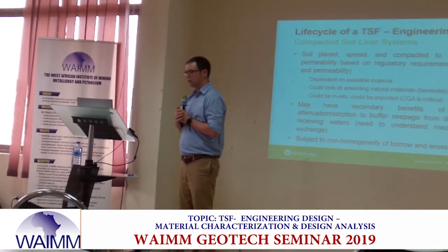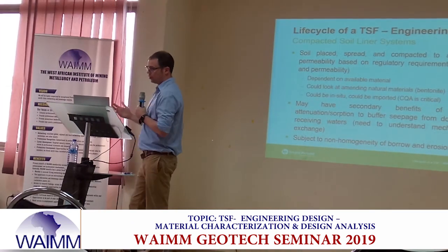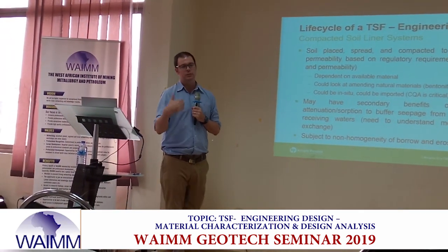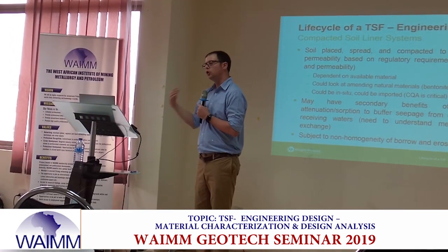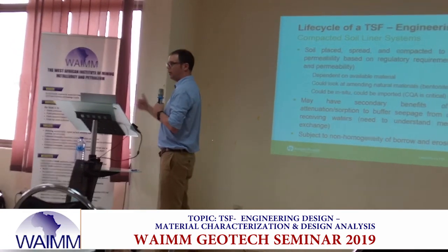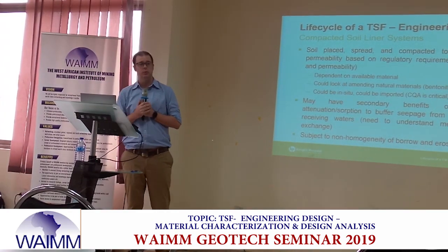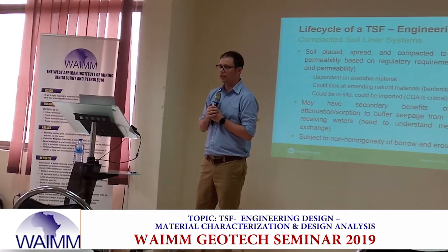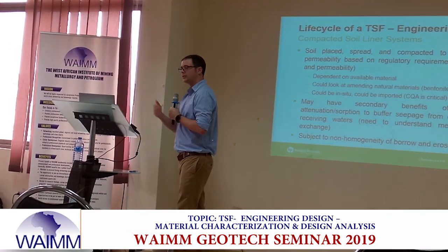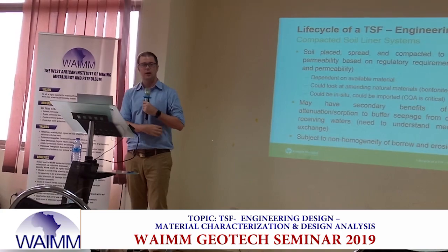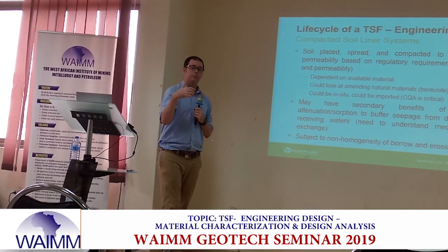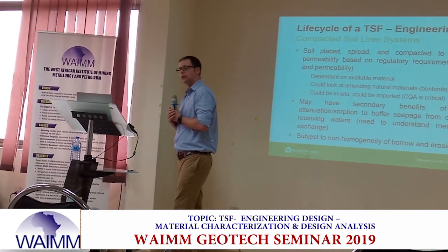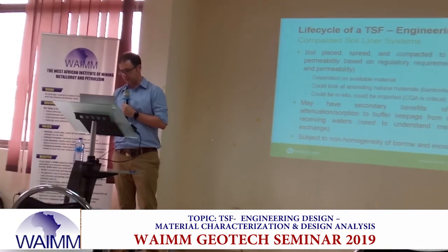There are some risks with using compacted soil liner, including non-homogeneity of materials. We need to have tight controls over those materials as they're going in, and good quality control on placement and on borrow. They're also subject to erosion in areas where we have high rainfall. We need to make sure that we've accommodated for the potential erosion of those materials, whether that's through continued maintenance of your compacted soil liner, whether that's through potentially protecting it with a fabric or protecting it with rock fill. Okay? So we just need to be thinking about those.